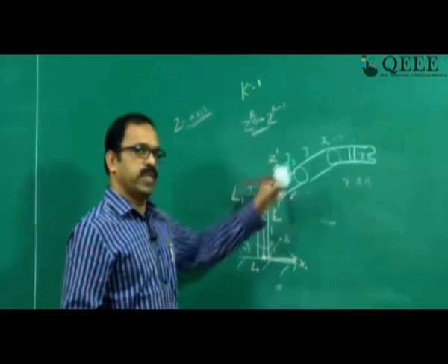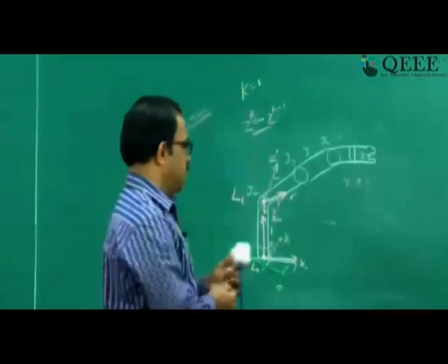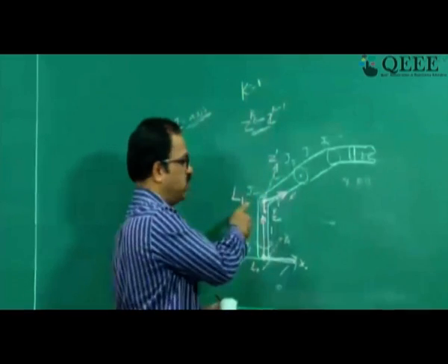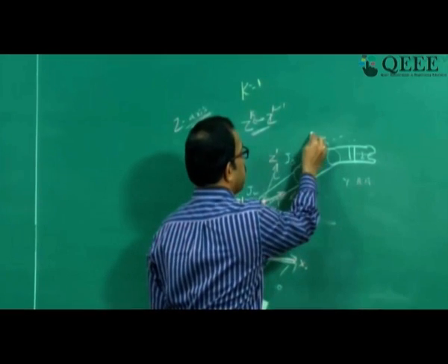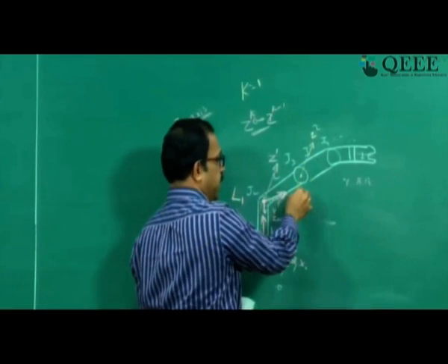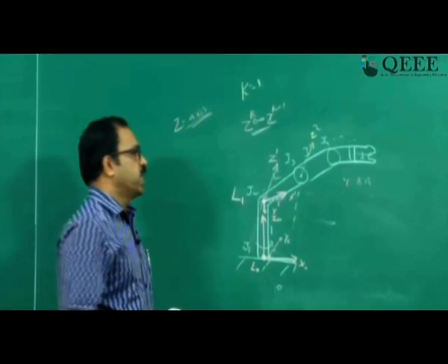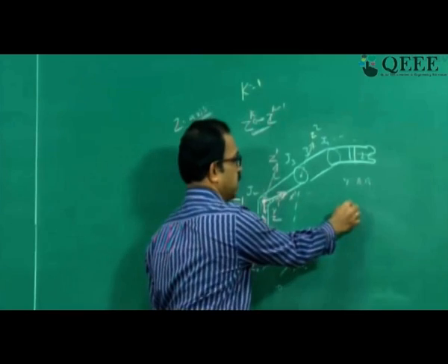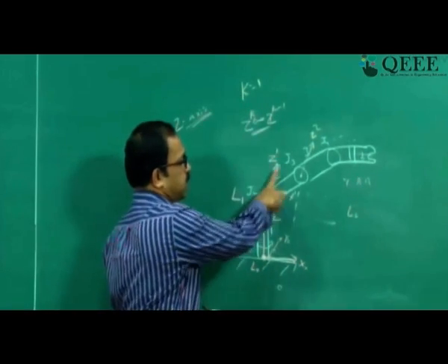Now we have to continue this for all the joints, because we need to apply the same algorithm. For this joint, again we know this Z1 axis, this also rotates about the same axis. So Z1 and Z2 will be parallel. This is the Z2 axis, because it will be like this and it passes through this, and we need to find out the intersection of Z1 and Z2 to get the origin. So L2, we don't know where the origin of the coordinate frame is. So what we do is, we look at Z1 and Z2.